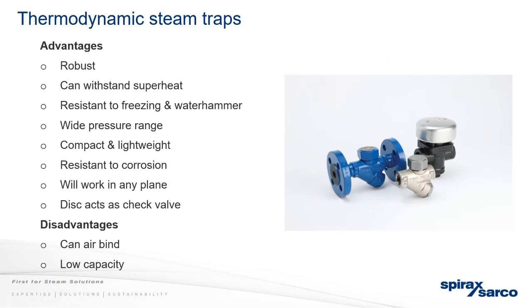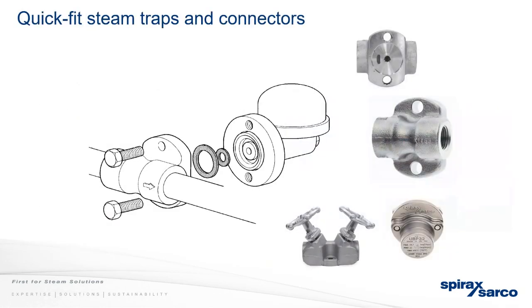So quick fit, we do a version where you can quick fit traps. As we show here, with this trap you have the quick connection here. They have a built-in check valve, I believe, so you can hot swap. These are very good where you want to speed up maintenance, where you have many traps. The disadvantage of these is they are lower capacity, but we have these options available too.